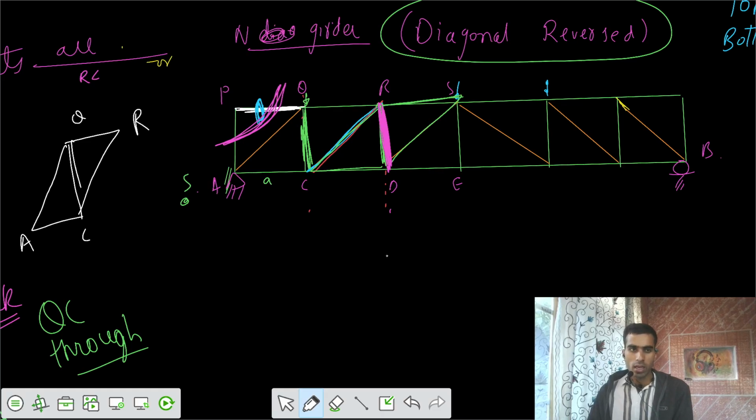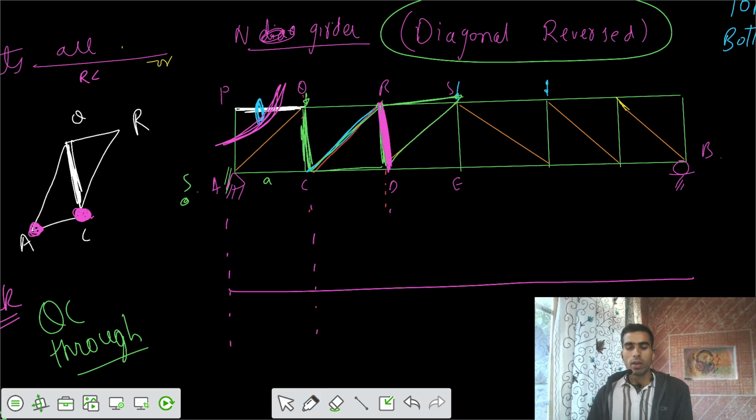Then after that, for this triangle, because the loading is through type, can you get the ordinates? Can you get those joints? Because of the through type loading, I would say peak ordinates. Peak gets developed at A and C. So one of the ordinates gets peak here, one of the ordinates here. So join them by a straight line. Now we need to get the values.